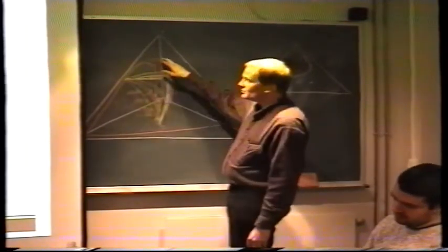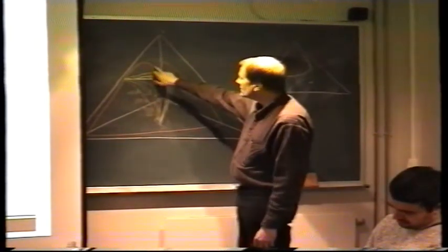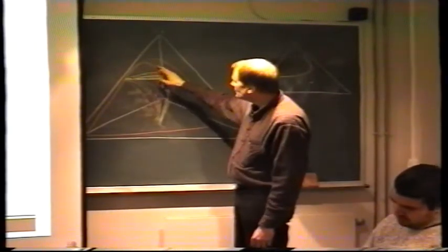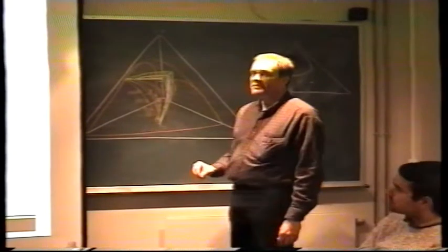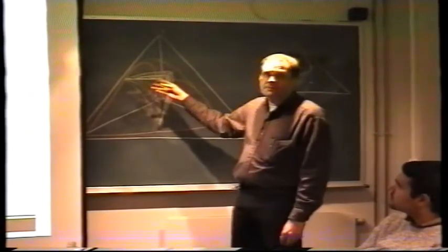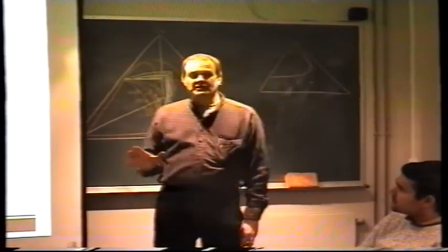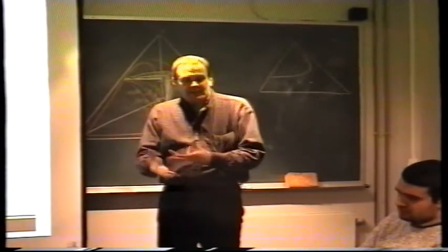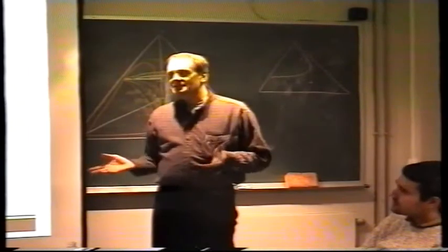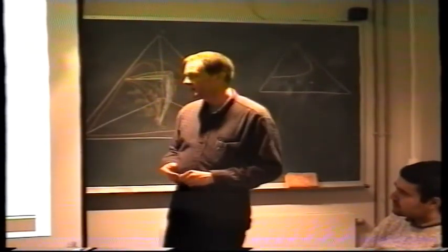You can put a critical point anywhere, like here, and say, okay, my solution is from this tie line to that critical point to this tie line. That's a solution to all their equations. It's not the stable solution. This is the only stable solution, but there are an infinite number of other solutions that the algorithm might converge to. And unless you check somehow for the stability of that final solution, you can't guarantee that you've calculated the right solution.